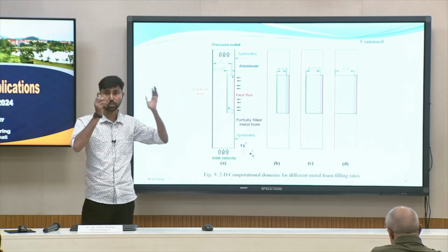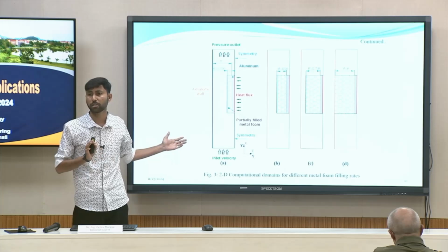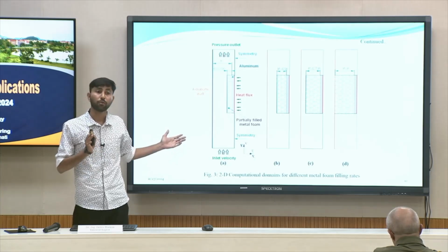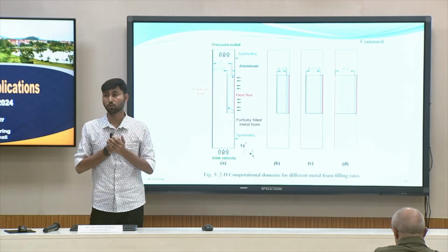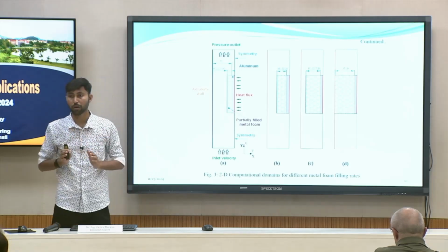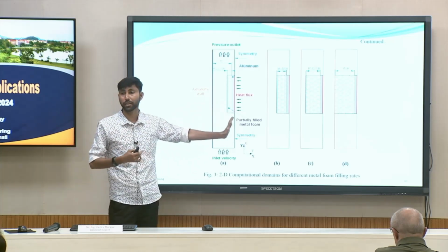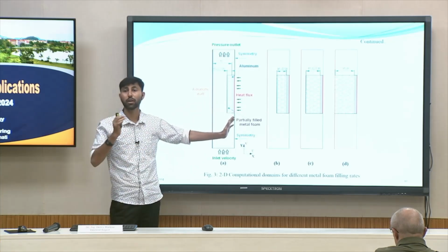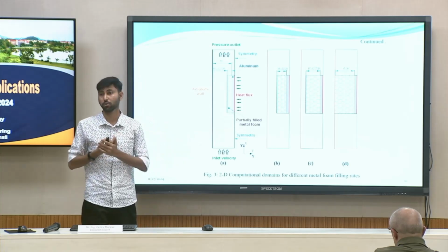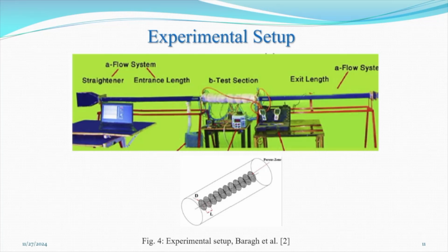If you concentrate only on heat transfer performance, yes, 100% is the best option. But we need to consider the pressure drop also. With the consideration of both heat transfer enhancement as well as pressure drop, we come to know that 75% filling gives a better result. So that is giving a good efficiency. This is what our results focused on. So that is one part of my work.